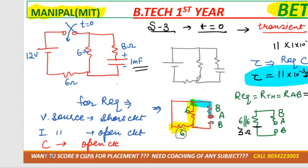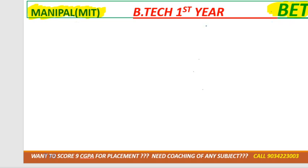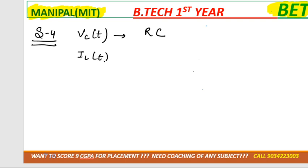In step number 3. Okay, clear? Now, after this, step number 3 is also done. We need to calculate the last and final step, step number 4. So what we need to calculate is VC of T if there is a case of capacitor. If there is a case of inductor, meaning an RL circuit, then in that case we need to calculate IL of T. Okay, so this is the case of capacitor.